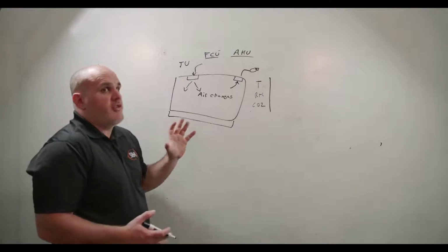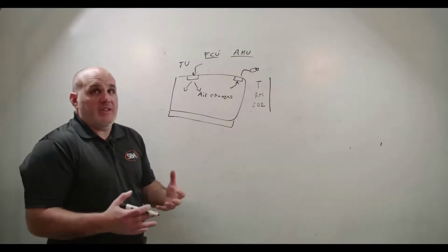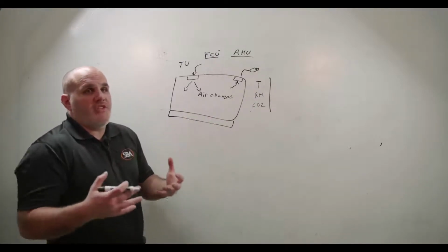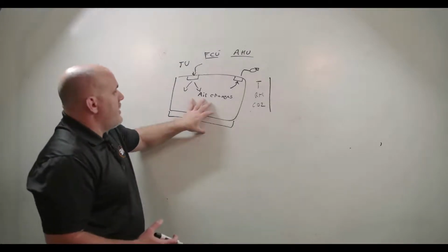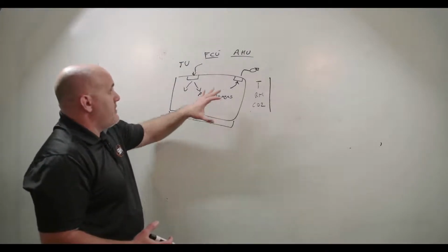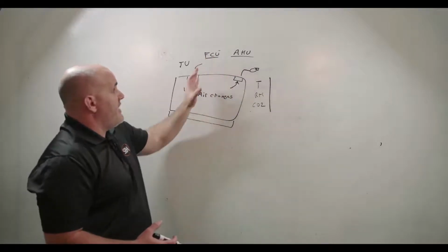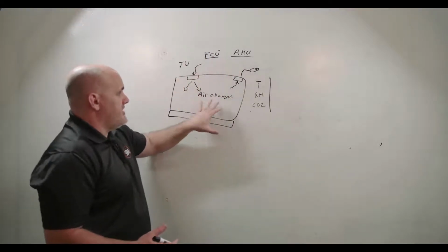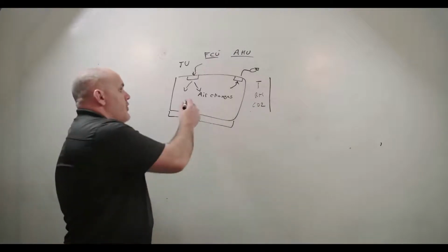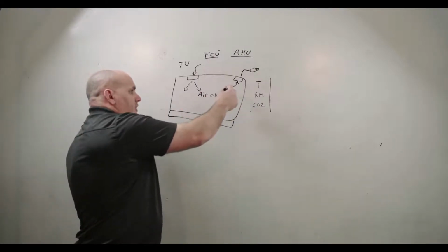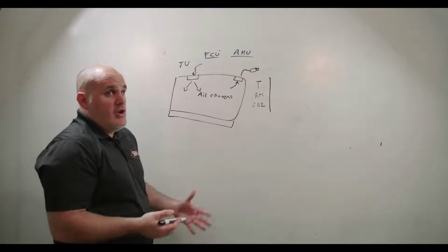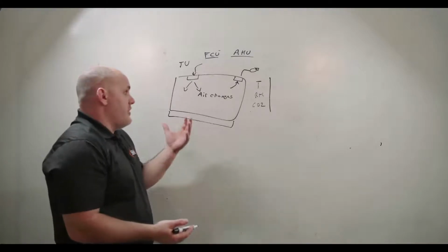But if we're looking for primary variables that we're going to encounter across most of our systems and most of our buildings, then we are looking at a typical air handler unitary system supplied to a space, a fan coil supplied to a space, or a terminal unit supplied to a space. Now, we match our outflow in what's called volumetric matching, or we do an offset in what's called volumetric offset.